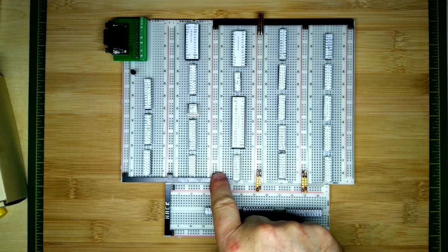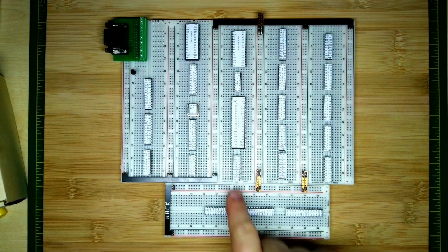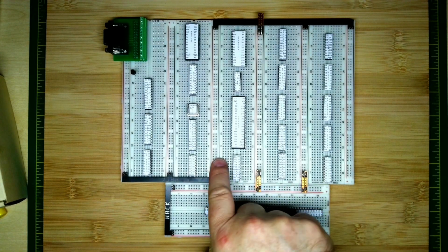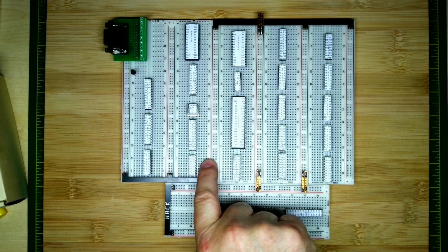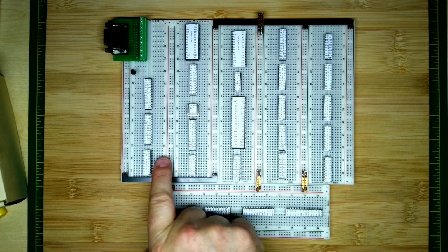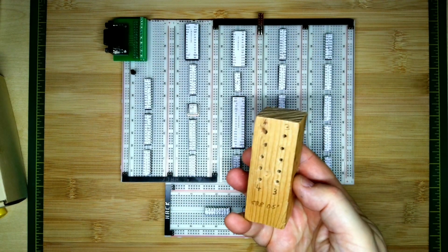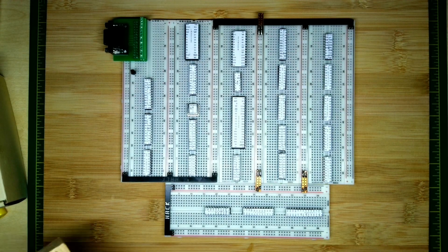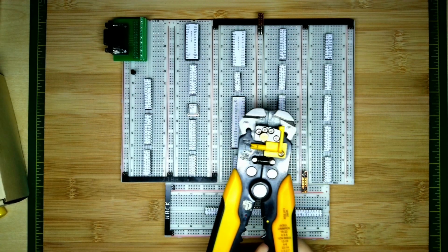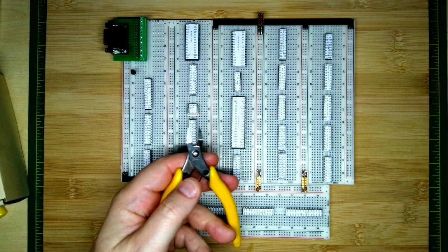A lot of these wires are needed for tying the power pins to the 5 volts and to ground, and we need combinations of 3-hole ones for when the power rail is close to the side there, and then you need the 4-hole ones for when you've got to go over the other power rail as well. So that's a useful little jig for making lots of those cables and making them more consistent, using the wire strippers and my cutters as well.